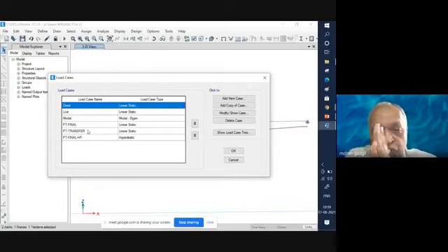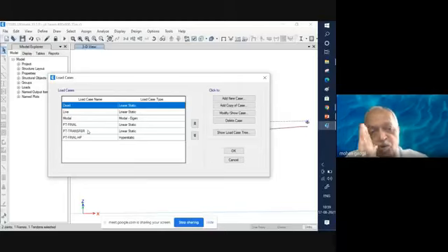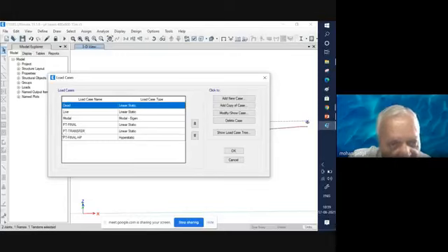So this is independent of the losses taking place. Losses will occur later on: the elastic shortening, the relaxation, the creep. All these losses will occur later. But at the initial stage, when you are just transferring the stress force, you have the full force applied except the slip loss, because after slip occurs, the cable gets locked. Accordingly, we have this PT transfer.